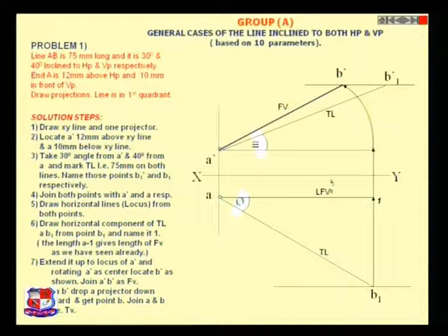Now you can have your front view and top view in one line itself. You can do two things from now. You can get your top view with respect to this front view by taking a perpendicular line to B1 from the B dash point, as you can see in red.